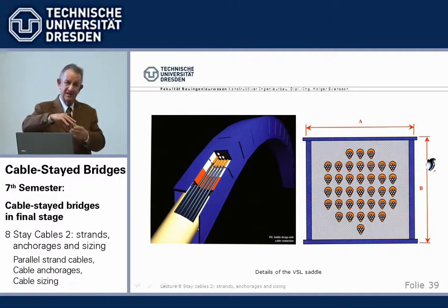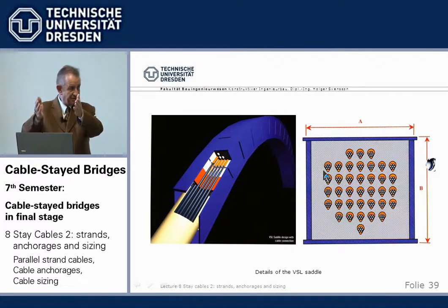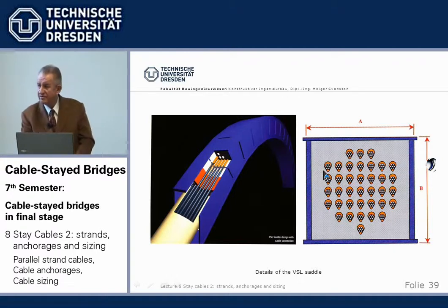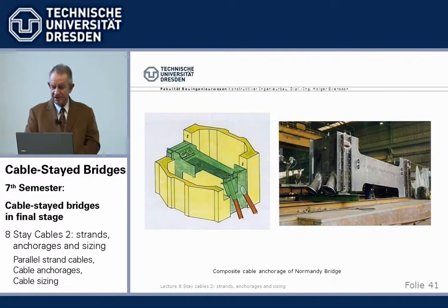So it's cast in, plus there are transverse plates which are V-shaped, and the individual strands run through, and by the force which is in there, they are pressed down and clamped into these V-shaped openings. So cast in plus friction in the V-grooves. That together gives up to 70%, they say, of live load forces, plus same fatigue range. Well, they have the tests. So that's the latest in saddles, but it is a little rare.